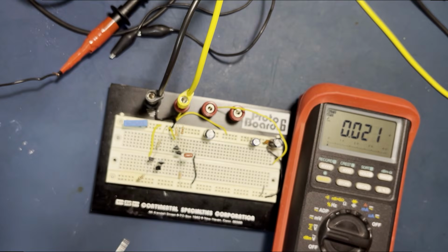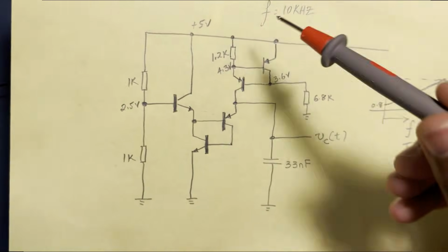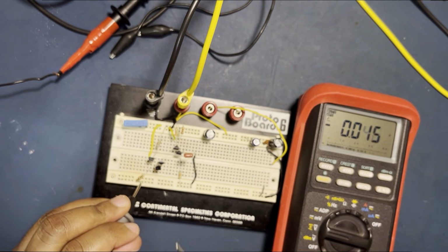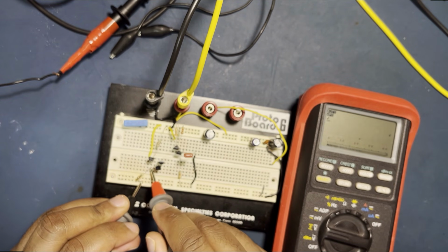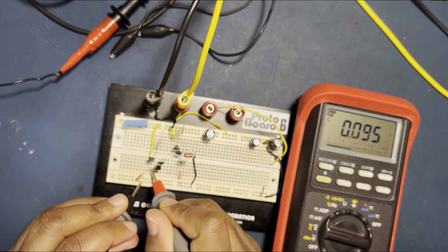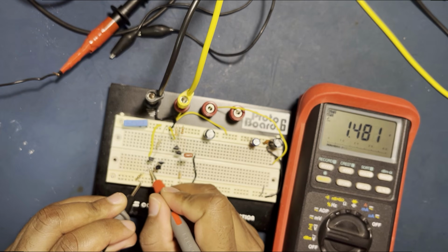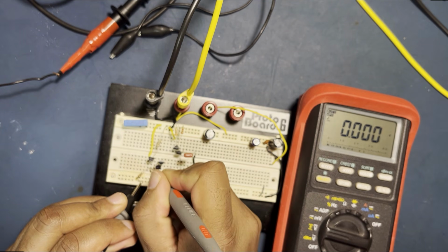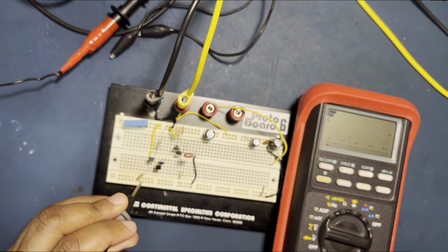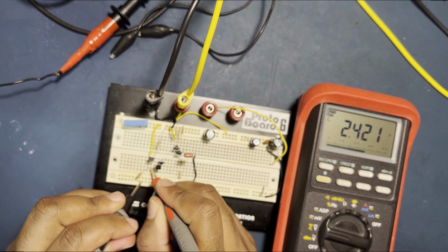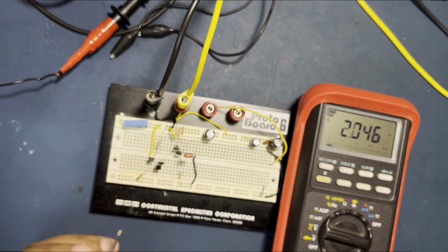So all right, so now let's measure this part here. Do we get half a volt? Obviously it's just a simple resistor divider. Let's take a look at what we get. It's this point here. Because it's oscillating, you can see my meter kind of detecting that, right? So the circuit is oscillating, right? So this has a high frequency bandwidth for the AC side. Okay, so there you go. So 2.5, right? So 2.513 is what we're reading. That's this voltage we just read.